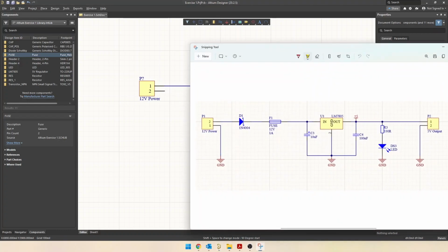Right, so let's have a look at what we need to do. Now we can see here we have this ground symbol, or ground net. Now with Altium, a net, like a ground net, is a symbol that is internally connected together. So these ground symbols, this wire here, all those wires, this one and this one, they are all connected together as far as Altium is concerned.